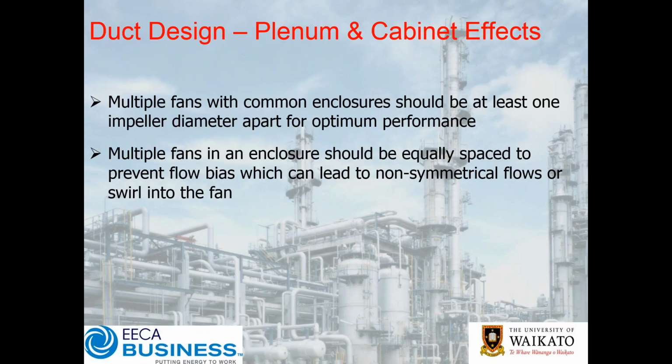Now that's okay, but you don't want to have high velocities in the actual room, blowing, having to get the air to where it needs to go. So you really do want that under 1, maybe at an absolute stretch 2, but ideally below 1 meter a second.